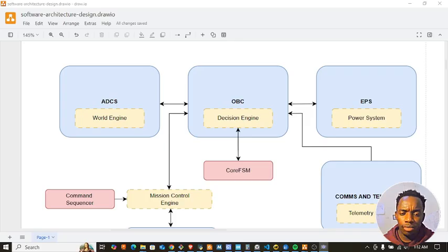Most of the time when you're doing firmware design, you have this concept of modularization of firmware. Everything is treated as a black box, so you only expose the interface to that black box. The APIs that are exposed are what are used by users outside. Users can be your driver code, the code that is using your modules, or a third-party plugin that is calling your inner core code.